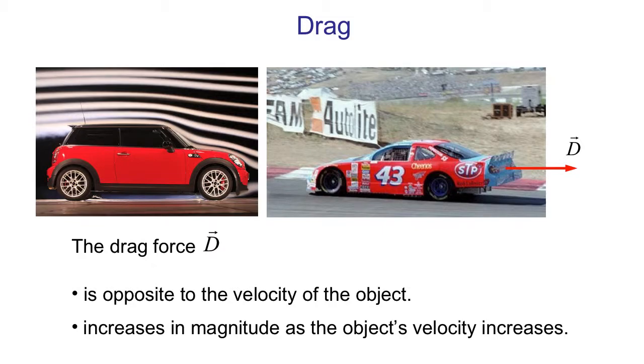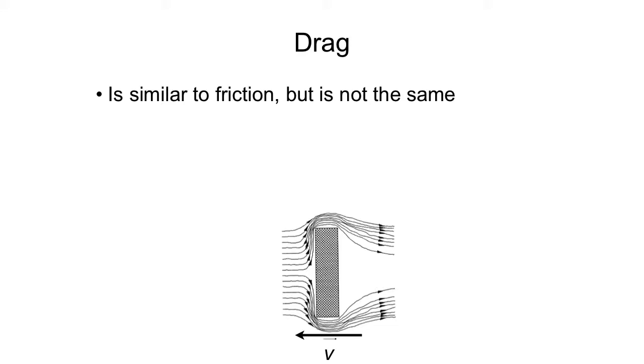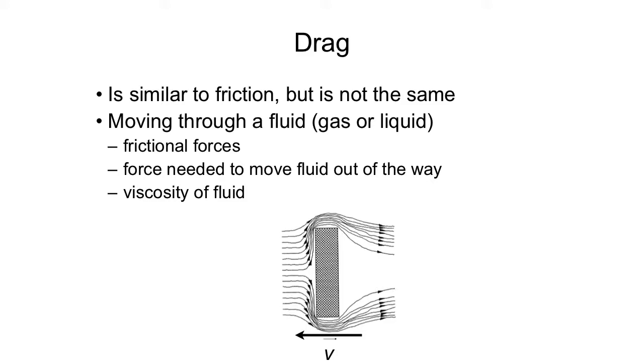So when we talk about drag, we don't just have to think about an object moving at a velocity v. It can be that the object is still and the air is moving past it at a velocity v. This is a question of reference frame. Okay? And we'll give some examples of that in a minute. But drag is very similar to friction. It's basically a property of the fluid that you're in. It's a property of the interface, what shape you are. But it's basically coming from the push of these air molecules against you, creating friction. So when I move through a fluid, whether it's gas, liquid, whatever, there are frictional forces. These are determined by, again, empirical laws. They tell how the kinetic friction of a molecule moves past this object.